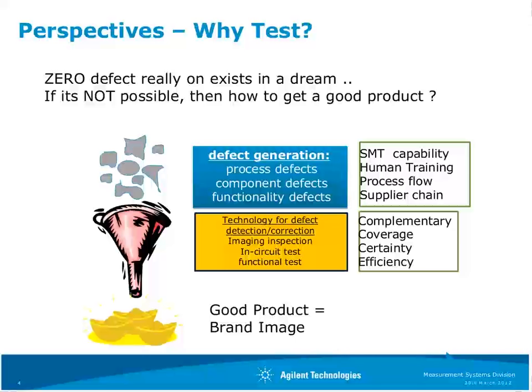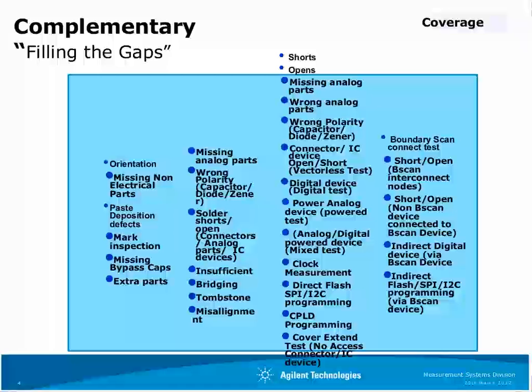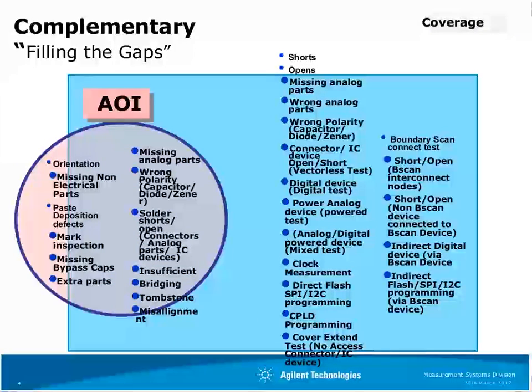The overall cost does come into play, and it is more acceptable to have overlapping test coverage in a low volume environment. But the defect coverage provided by test stages in low volume is critical and needs to have a high defect detection capability. Typically, this type of manufacturing defect coverage is only achievable from high-end in-circuit test platforms. Complementary test is providing the coverage for the gaps, but we still need to balance visual and electrical.